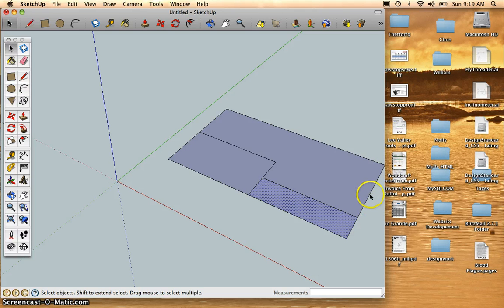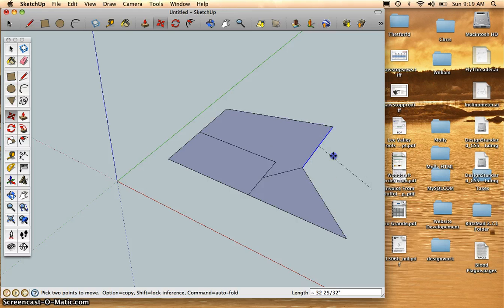With the selection tool, I'm going to highlight this line segment. Google SketchUp uses something called sticky geometry. If I use my Move tool, which is this one up here, or in the larger tool set, it's over here, and I move that line segment around, notice that everything that is attached to it moves with it. That's because the endpoints of that line segment are being moved, and they determine where the other lines end.